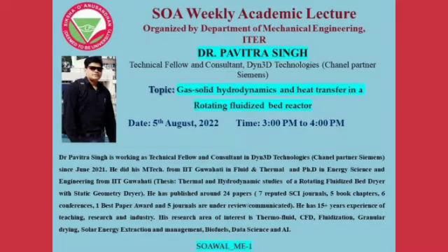So actually I would like to discuss the advantages and applications of this rotating fluid bed reactor. Actually, this is a very compact size reactor through which a large amount of air interacts with solid particles, and due to higher solid slip velocity, higher heat and mass transfer is possible, and this higher heat and mass transfer makes the drying process faster. So we can perform various operations in this reactor such as particle coating, milling, separation, mixing, gasification, combustion, drying, and I am trying to use it as a milk dryer.